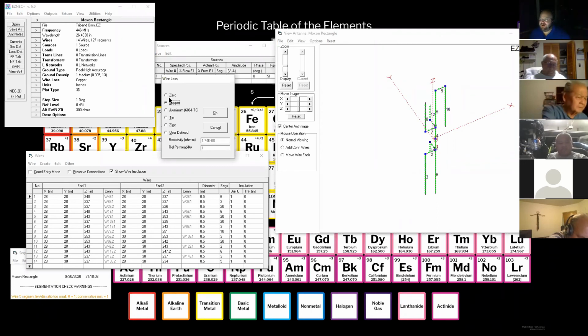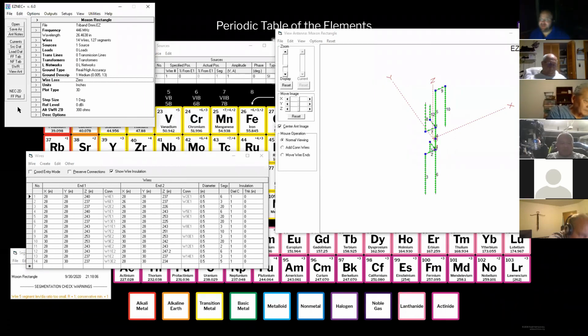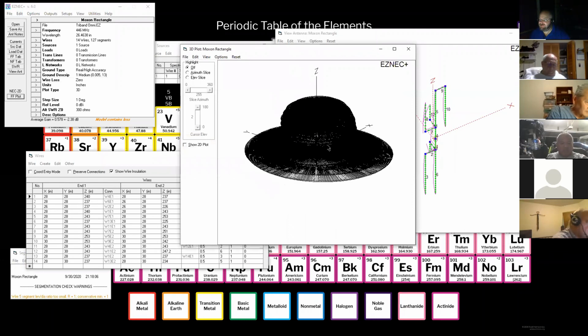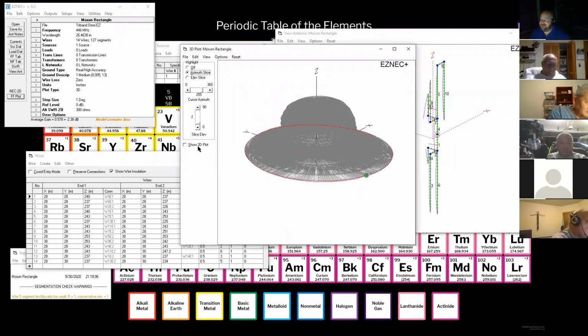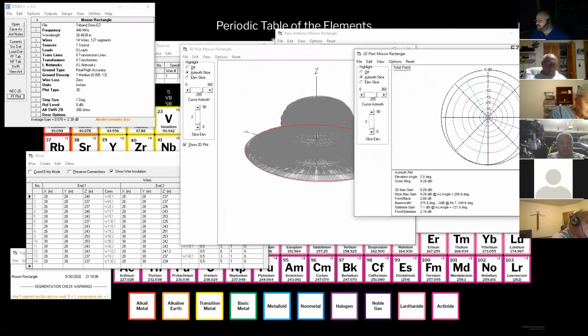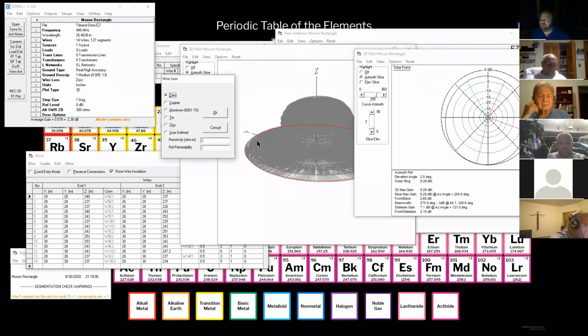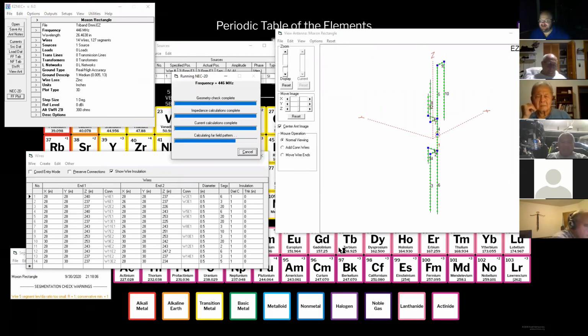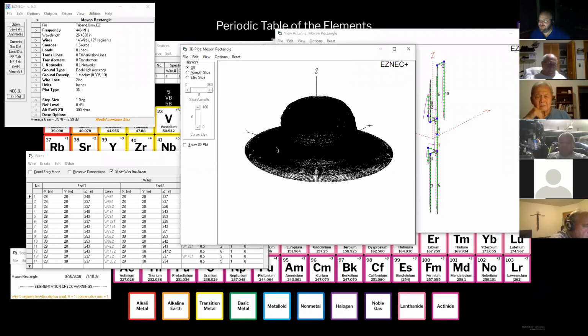So here, I'm going to go to zero loss, and I'm going to look at my gain here for 70 centimeters. It's going to say I've got 9.29 dB of gain if I've got zero loss in the wire. Now I'm going to come back here and go to zinc, which is horrendous, and rerun that antenna as if it were made out of zinc or zinc-plated wire.